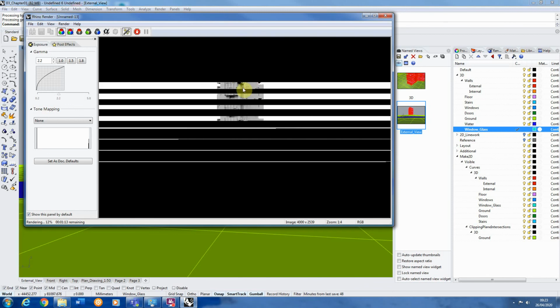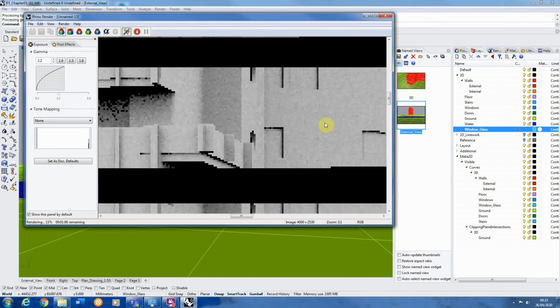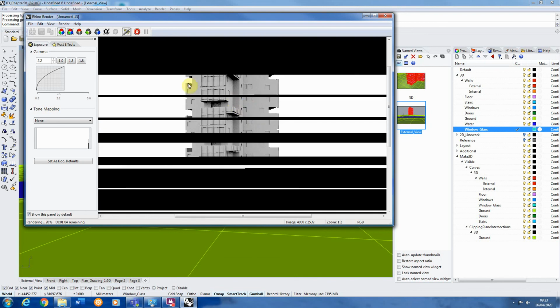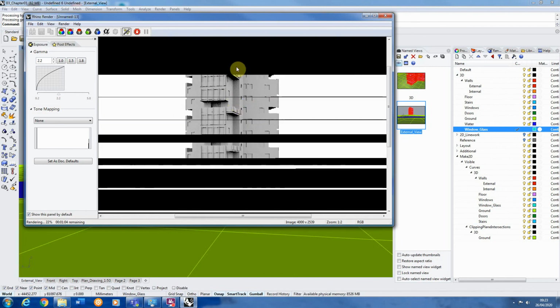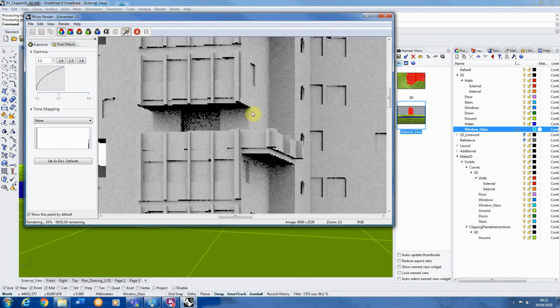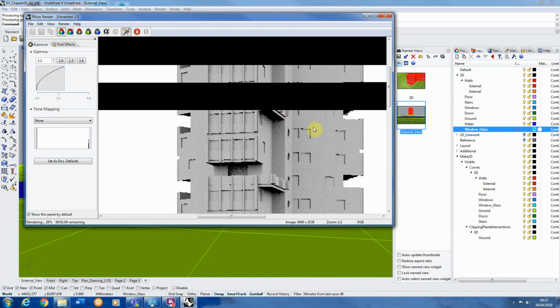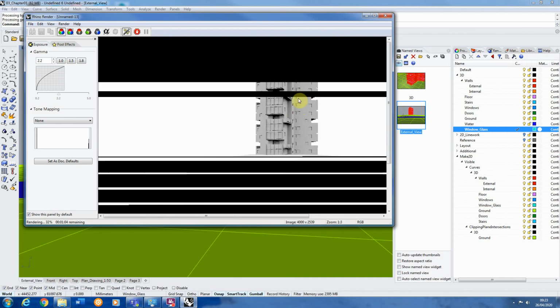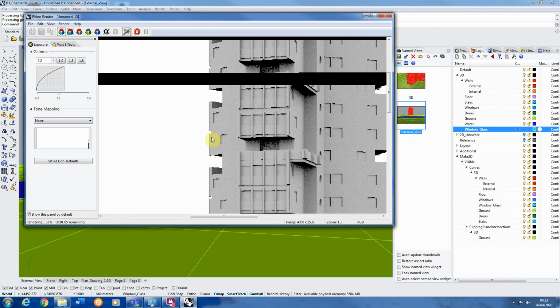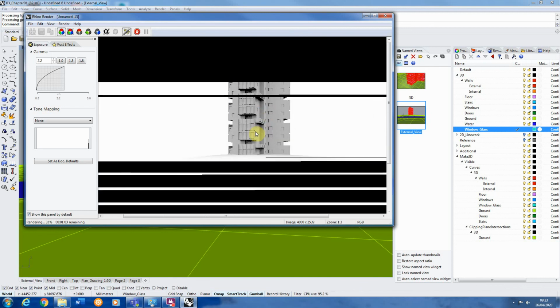Now you'll see it's a lot slower to render out because the skylight kind of renders this ambient lighting, which is a lot harder for the computer to compute. And you'll see it's usually a little bit grainy as well, and that's just the kind of nature of using that lighting system because it gives a kind of overall light, not a strong shadow. It's a bit more difficult for the computer to work out, so renders a little bit slower.